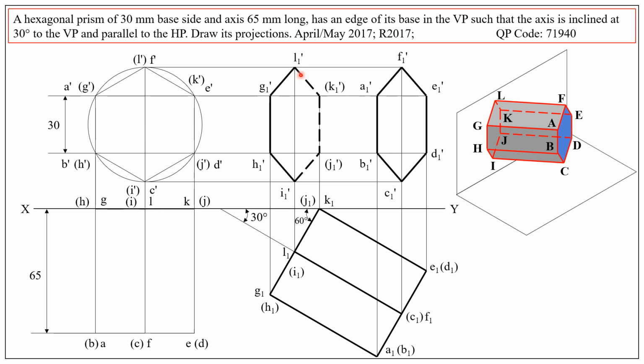One crude method or rough idea, which may not work always, is to consider the points between which you need to draw the line. So I1 dash, J1 dash. J1 dash is invisible. So whenever you encounter an invisible point, draw a dotted line. J1 dash, K1 dash, both are invisible, dotted line.